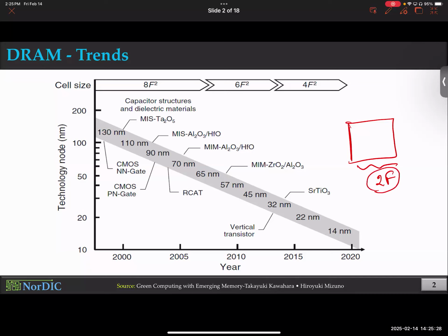So if you think about a rectangle, maybe a memory cell, what is the absolute minimum layout optimization you can get? In horizontal dimension, if I get 2F, in vertical dimension, what can I get? Absolute minimum. 2F again. Do you guys all agree with it? There cannot be any further optimization. The moment I get to 2F by 2F, it's fine. My layout is fully optimized. I cannot optimize it anymore. Are you guys all with me?